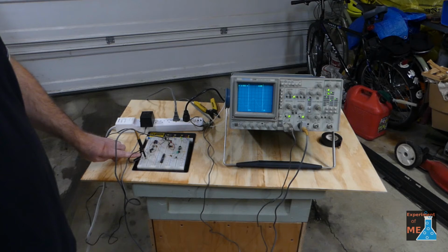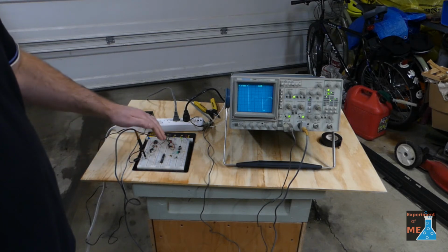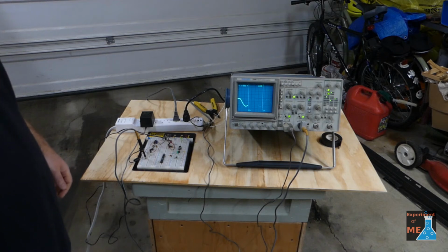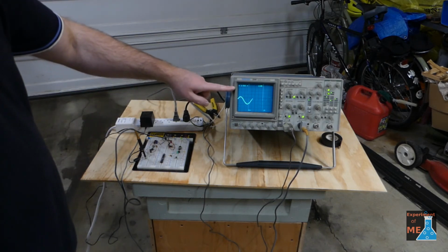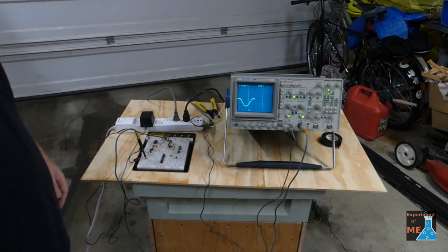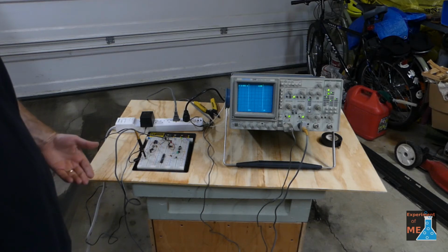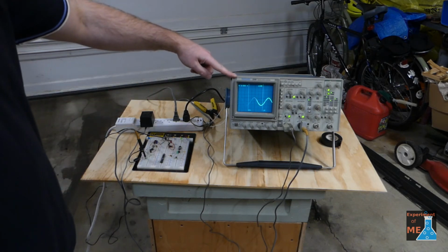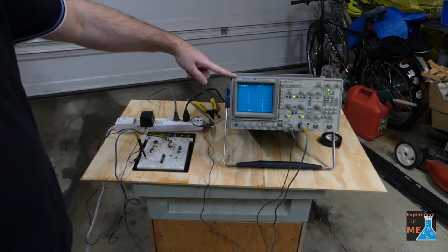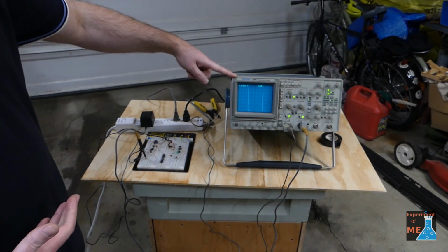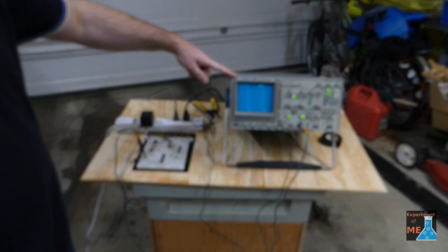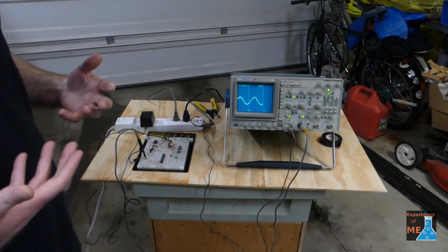And so I know that it's a light detector because if I turn off the lights, we'll see that the voltage will go all the way up and it'll be a constant voltage versus this alternating voltage that we're seeing. Now the reason why we see the alternating voltage is because the power into my house is alternating current, or AC, and so that causes the lights to flicker as well.